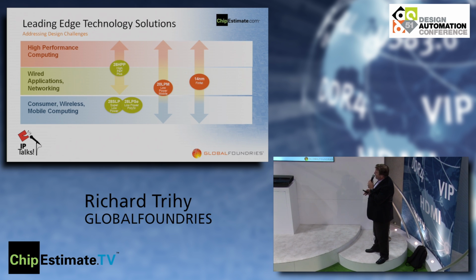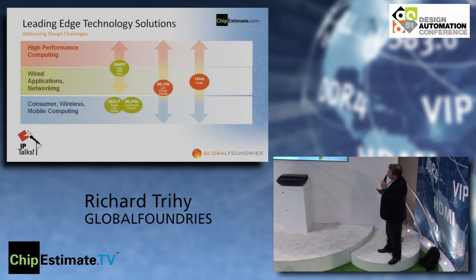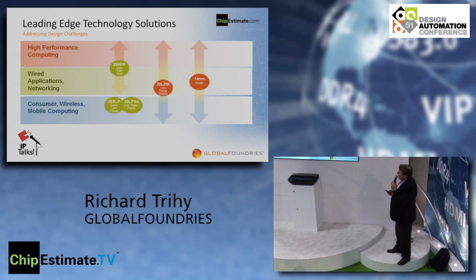So in the 28 nanometer space, we have a high performance 28 HPP targeted at high performance computing and network applications. And then for low power, we've got two solutions, 28 SLP, also high K metal gate, and a polysilicon process, 28 LPS. Our 20 nanometer process extends the whole range from a low power variant all the way to high performance. And we also have a 14 nanometer FinFET process.